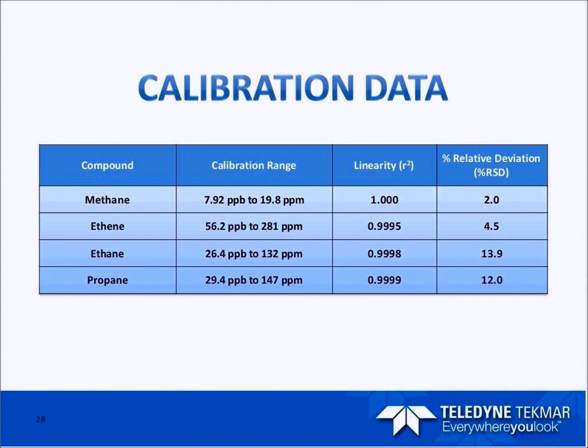We're very optimized for methane and ethene, because they're the quickest ones to come out and the easiest to purge out. We didn't want a middle-of-the-road set of purge parameters, because it would probably hurt methane most of all, since it's the most volatile, most challenging compound on this short list.